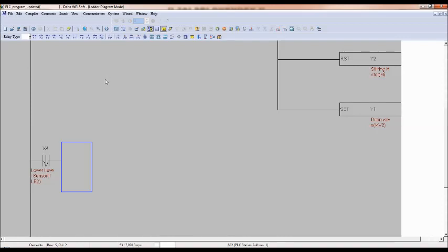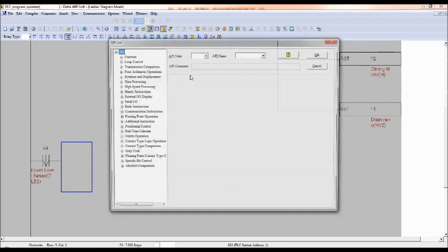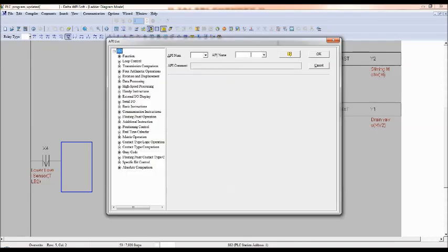So we have to take the data to a system variable called M1, and for that I will use set. I already discussed how to use falling edge detection or rising edge detection in the program. So we have to use the set function for that, right?